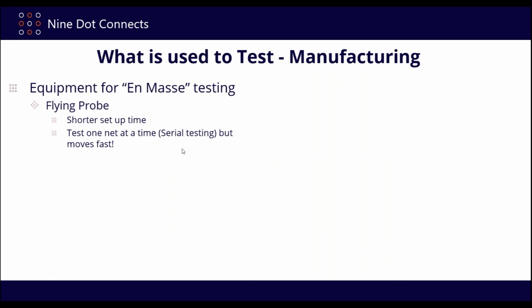That's what it's doing, but it's doing it pretty much in a serial fashion. And what is it looking for? These are really good for continuity tests. So what are continuity tests? Well, when they've made the board, the signal is going to travel from point A to point B. So they're going to check for opens. They're also going to check for power shorts against the signals as well. And they'll also check for resistances.